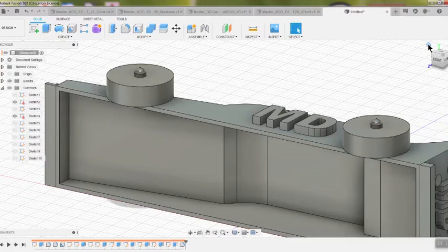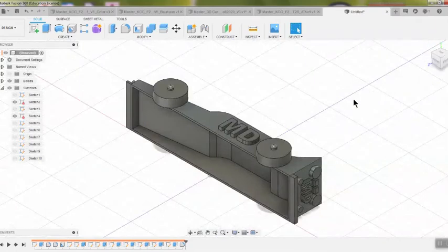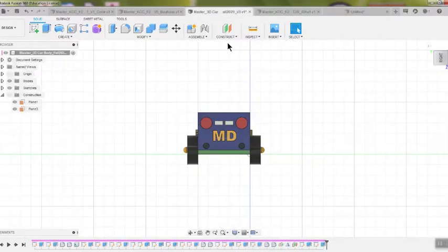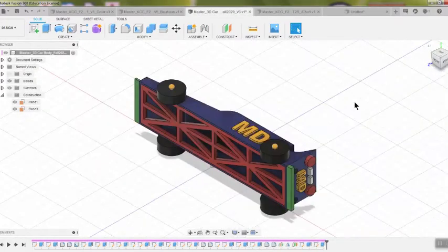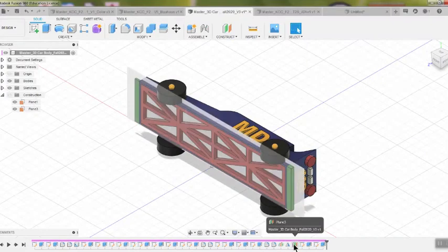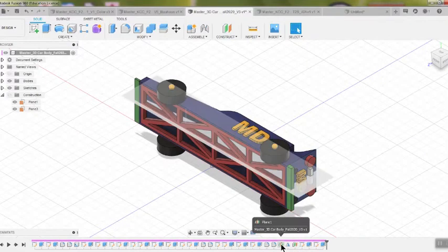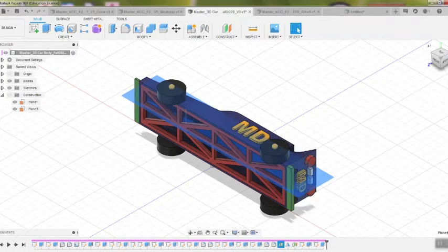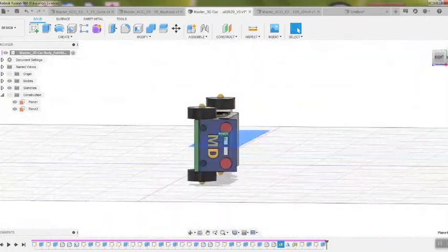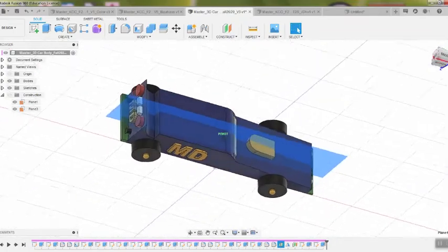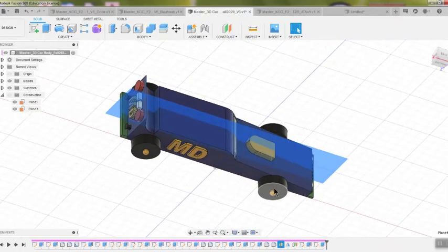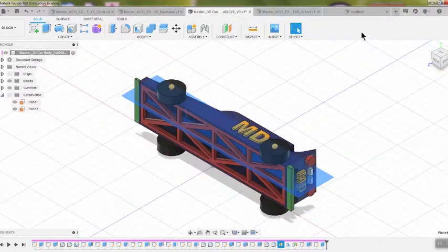And let's hit the enter button. And let's left click and release the home button. And there we have it. So we have our axles, we have our wheels. Now, if you remember from the previous drawing that I already did, we wanted to get this mid-plane in. So then once we get the mid-plane in, we can mirror the wheels and the initials to the other side. All right, so let's take a look on how we're going to do that.